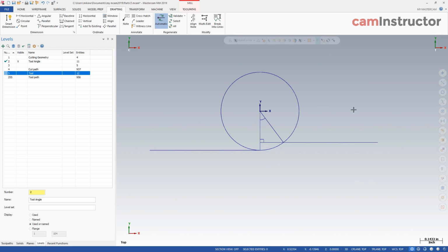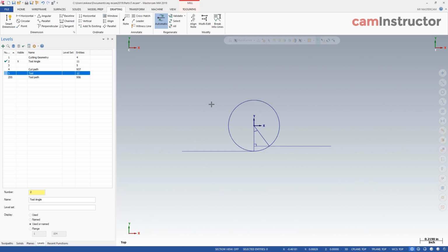One scenario is this one here. So we're cutting straight in one direction, engaging a consistent amount of geometry. Scenario number 1 would be where stock falls away from, or the cutting path falls away from the direction of cut. And the other scenario would be where stock actually falls up towards the direction of cut.